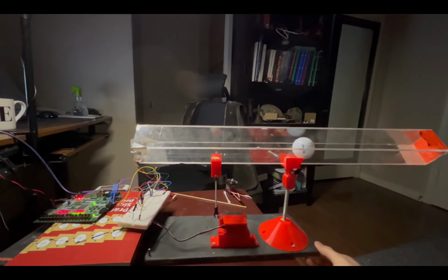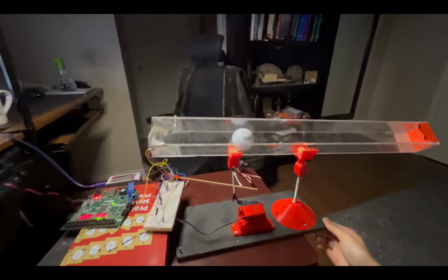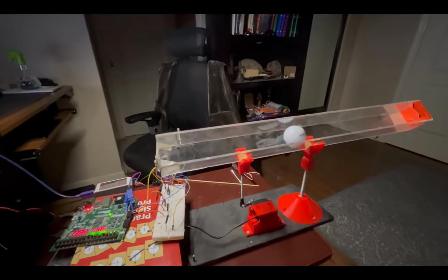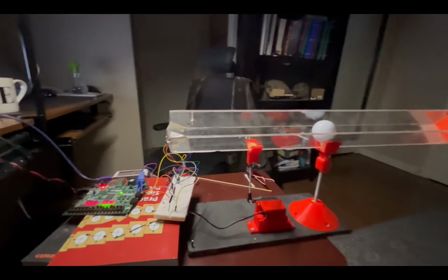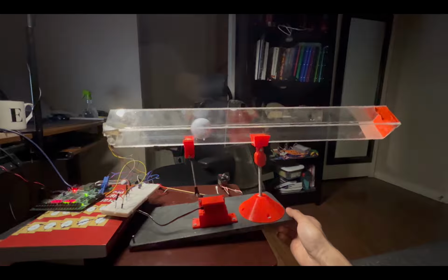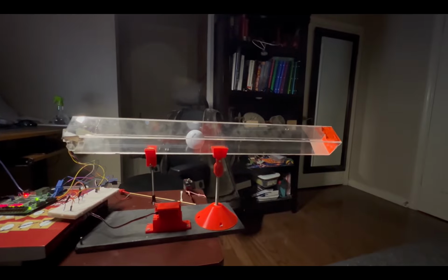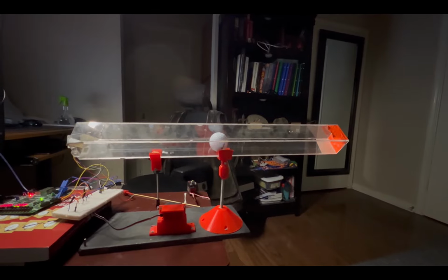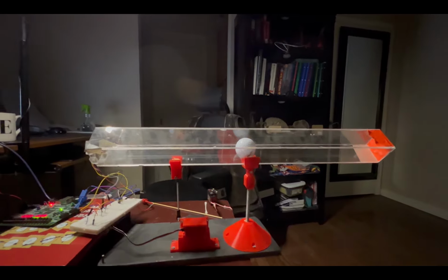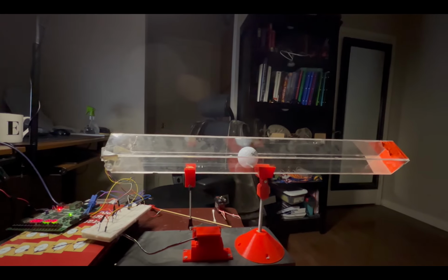So there you have it. We've now successfully built a PID controller using the proportional and derivative components. I'll leave it as an exercise for you to add in the integral component. As a quick warning, the integral term takes time to become usable. Clamping and stabilization are required to prevent instability and ensure smooth performance.